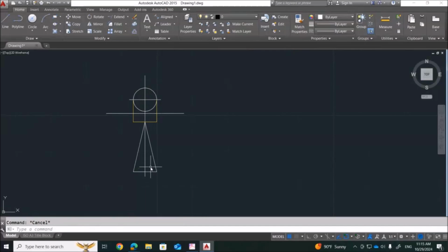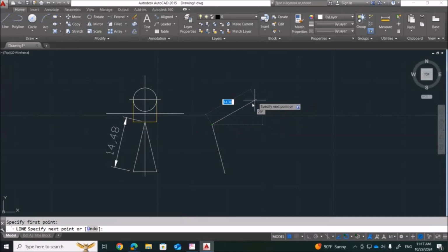Now I want to make this cone, so I need to make surface development. So if I open this and measure this align length, because we don't know this, so this is 14.48. So that's why I choose 2 decimal. Understand? Precision 2. So line, I will click here line and I will draw any angle. How much length? 14.48, enter. Any length. Now another line I need to draw from here if I develop.